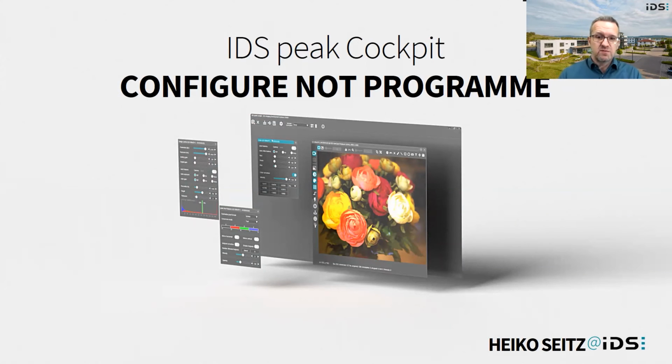For example, when it comes to perfectly adjusting a camera for an application situation with the help of histograms, saving this in a configuration file and using it in a later application. This way, you can configure a big part of the application preparation instead of programming. Furthermore, error cases or other special situations can be analyzed in a systematic way.